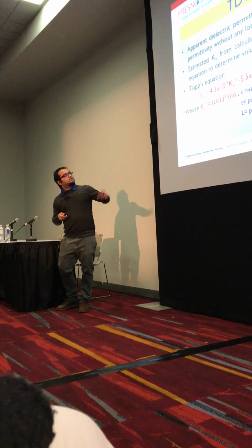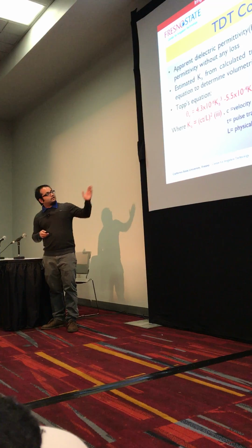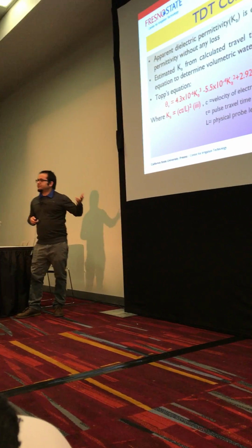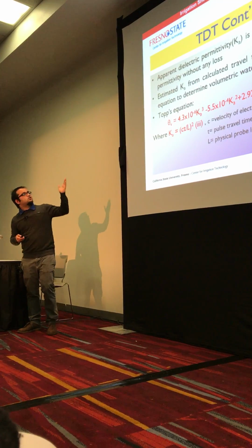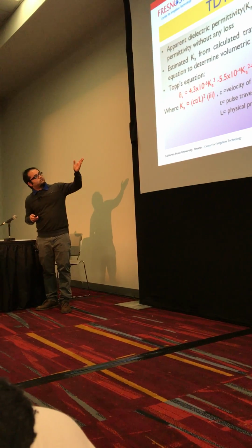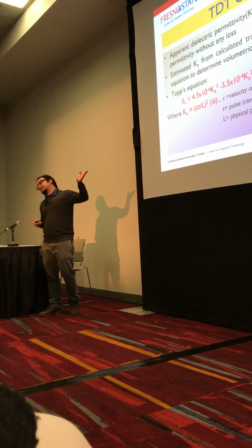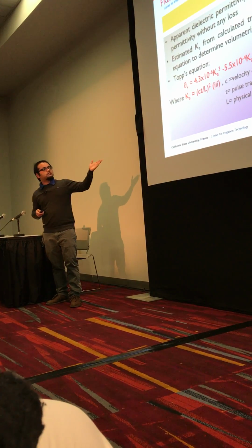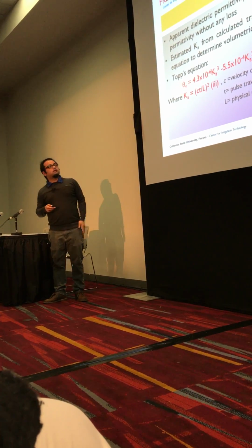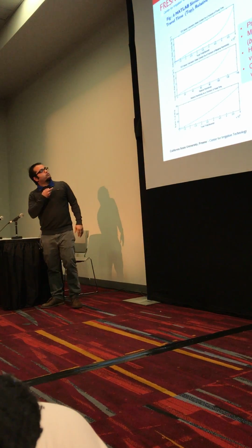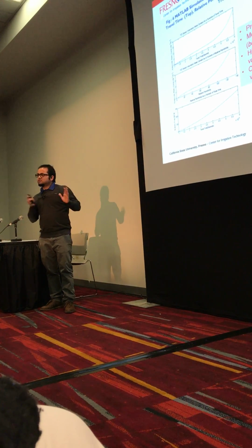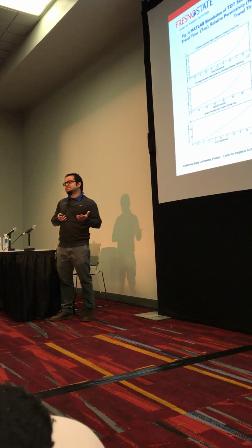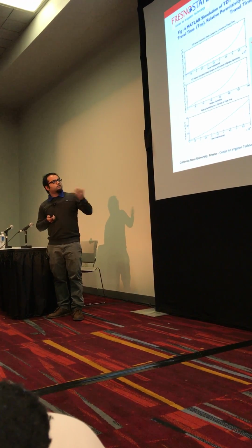And this is the equation, we call it the Topp equation, that is used based on the travel time, and it determines the relative permittivity, which for the moisture sensors we call the equivalent dielectric, also called apparent permittivity, represented by Ka. We just put this in the Topp equation to get the volumetric soil water content. And we did a MATLAB simulation for this to see how these terms, like permittivity and travel time, can affect the change in volumetric water content of the soil.